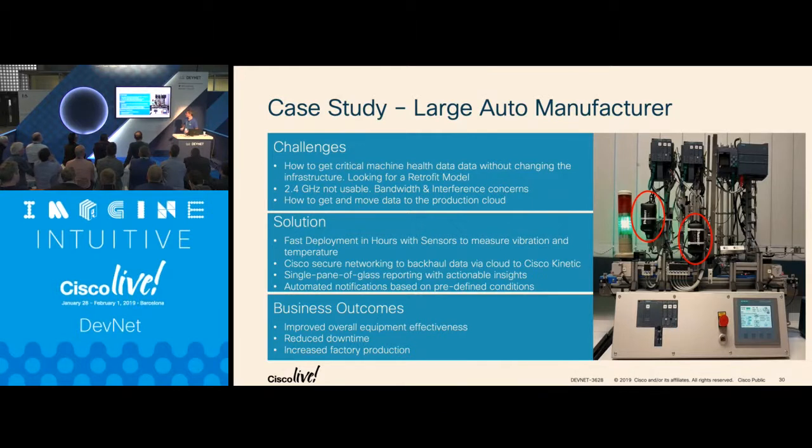Okay, we deployed this at a German manufacturer. This is a mock-up of a machine. As you can see, we have sensors. Sensors are actually wired over here. So we can monitor the amount of time the arms are in motion, for example, because there is a gyroscope in there, the average vibration, dominant frequencies, and things like that. If you see that, generally speaking, it takes 20 milliseconds to do a movement, and suddenly it's 21, 23, 25, I bet something needs to be lubricated somewhere because it's not really moving as fast as usual. Just an idea.